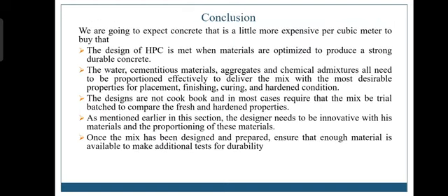Conclusion. We should expect concrete that is a little more expensive per cubic meter to buy. The design objective is met when materials are optimized to produce a strong, durable concrete. Once the mix has been designed and prepared, ensure that enough material is available to make additional tests for durability. As mentioned earlier, the designer needs to be innovative with the materials and their proportioning.